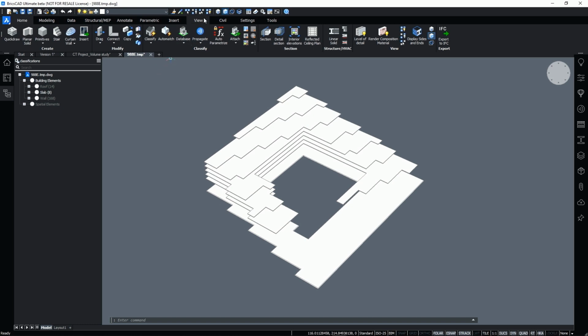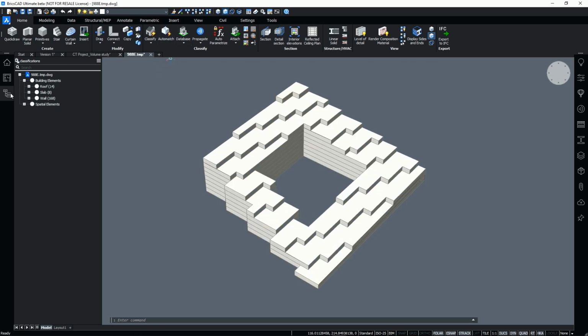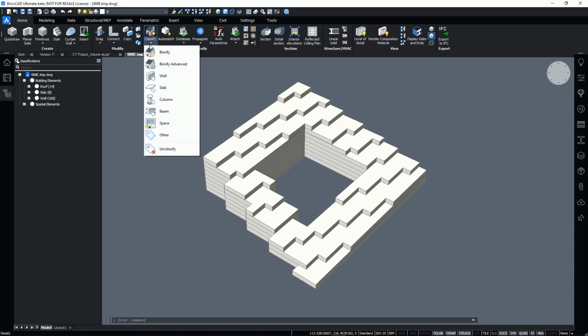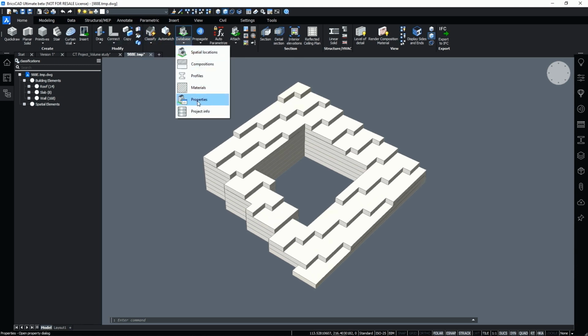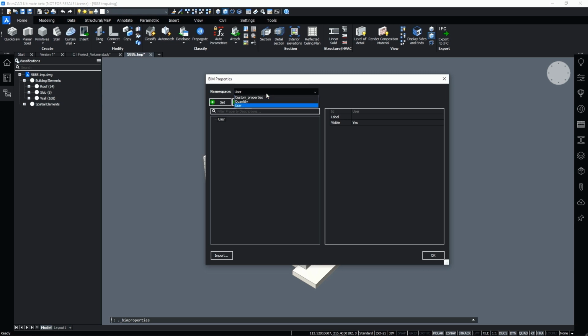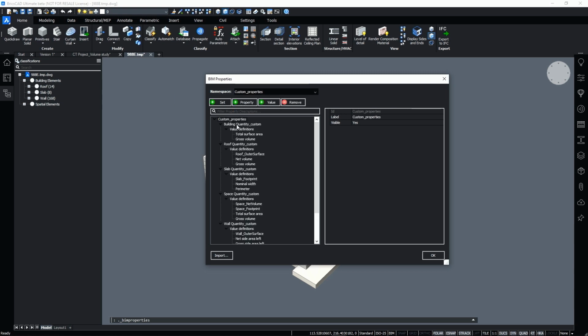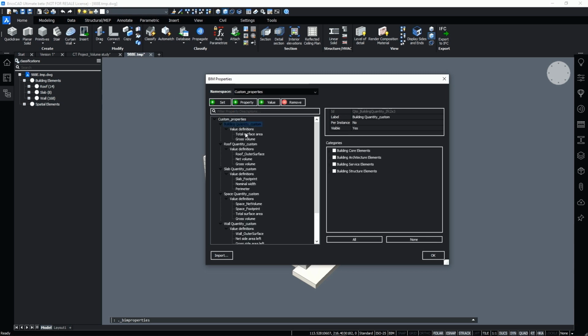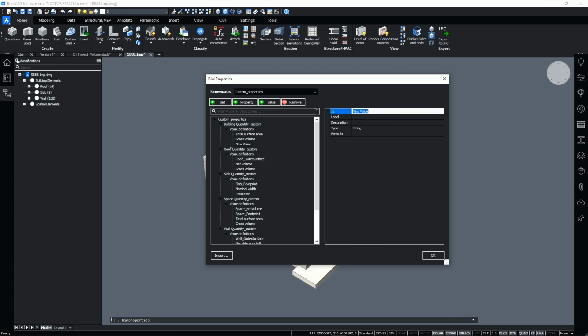In this way, it is not only possible to compare design alternatives in a geometrical way, but also compare them using different derived quantities. As part of BricsCAD V21, we have introduced a new quantity framework that allows users to create configurable user-defined quantities. We have prepared some quantities up front, but of course it's also possible to create your own quantities using expressions like sum, max, or min.